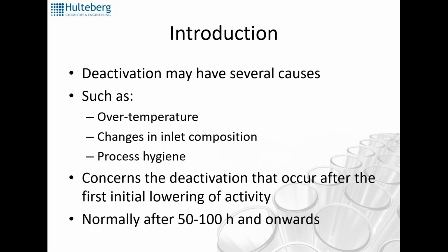And to me, deactivation is what happens after the first initial lowering of activity. When you start working with a catalyst and it's fresh, there will be some initial decrease in activity. There will be recrystallizations. The metal clusters on the surface will find their final configuration, combining with each other.